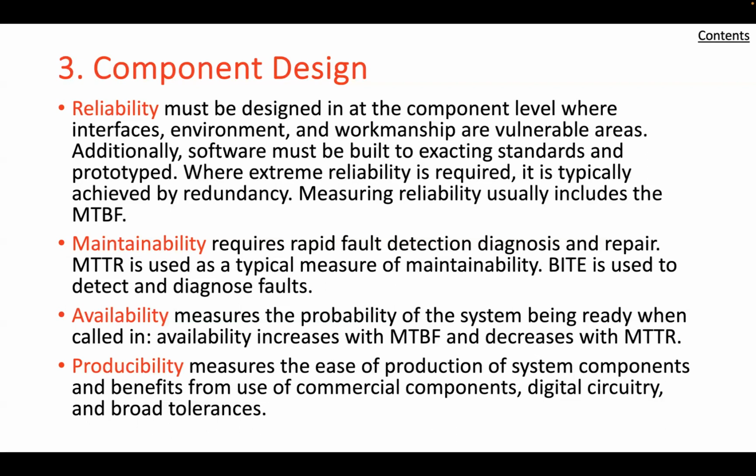Let's talk about maintainability. Maintainability of a system is a measure of the ease of accomplishing the functions required to maintain the system in a fully operable condition. System maintenance takes two forms. One, repair if the system fails during operation. Two, scheduled periodic servicing, including testing to detect and repair failures that occur during standby. High maintainability requires that the system components and their physical configuration be designed with an explicit and detailed knowledge of how these functions will be carried out.